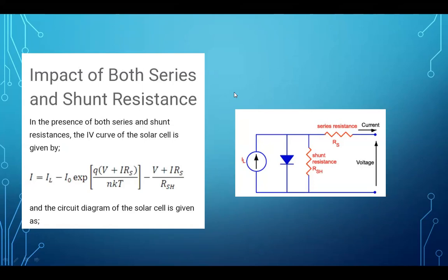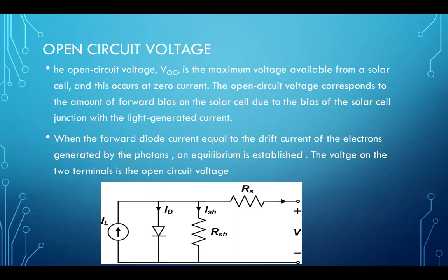So what I will measure in my experiment is the internal resistance, which consists of both of them. How can I measure this, as we are working in the lab? Going back to the open circuit: how can I measure it? I will have my solar cell and I need to make this circuit open, so I remove the load. I have no load at first.